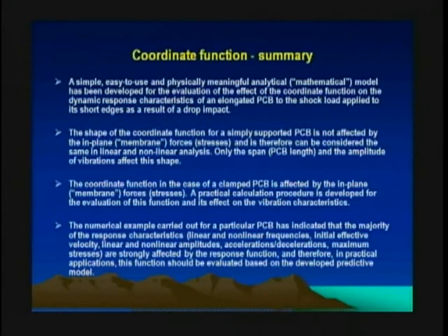The shape of the coordinate function for a simply supported PCB is not affected by the in-plane membrane forces, and therefore can be considered the same in linear and nonlinear analysis. Only the span, PCB length, and the amplitude of vibrations affect this shape. The coordinate function in the case of a clamped PCB is affected by the in-plane membrane forces, and a practical calculation procedure is developed for the evaluation of this function and its effect on the vibration characteristics.